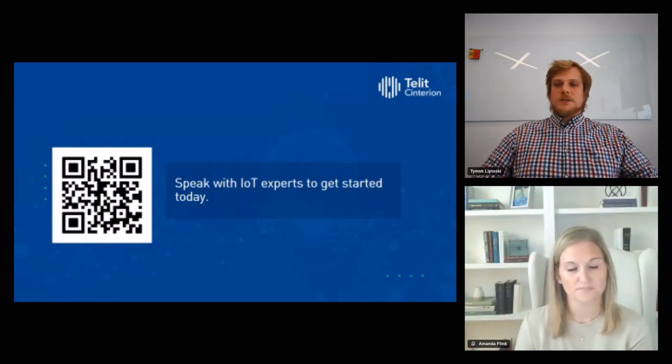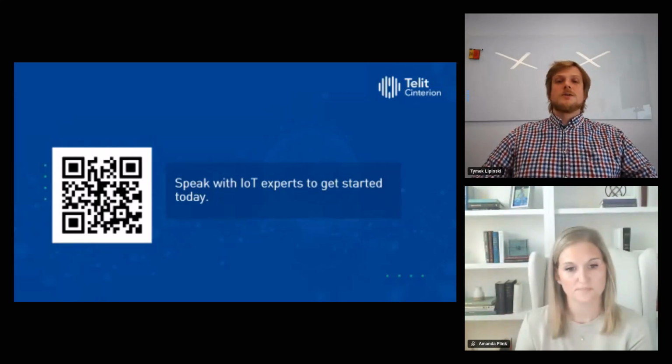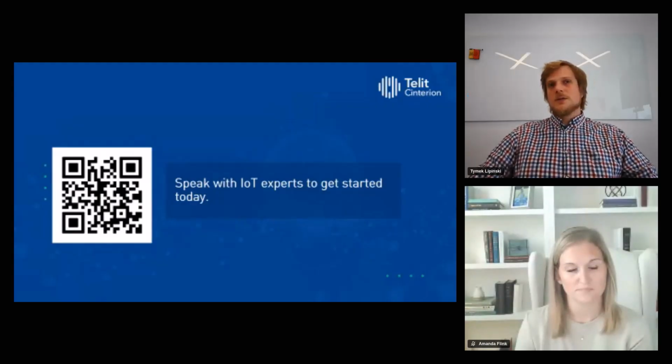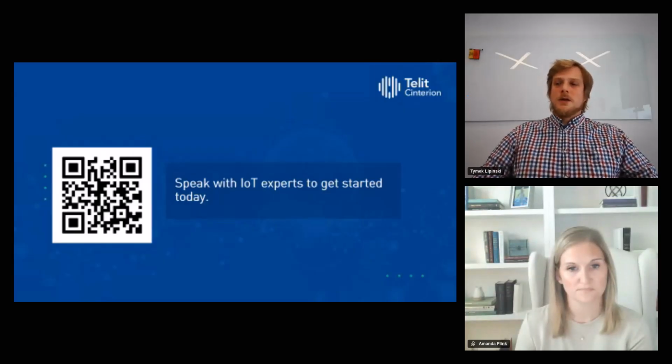And this is how they achieve a low-cost device with pretty much no wasted energy for sustaining the operation. And the best thing I have observed so far and had experience with was using NB-IoT with PSM suspend mode enabled in such a hardware situation, and using the release assistance indicator with the network and using UDP transfers. So throw a packet, expect or don't expect an answer, throw the release assistance indicator, and go back to sleep. Basically, the devices I have met are meant for metering and working 5 to 8 to 10 years in the field without any service requirement.